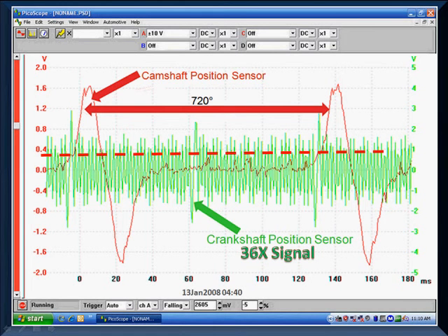Now, here's a high rate system. On the newer vehicles, when we get the coil on plug, we're going to have this type of system. Let's look for the signature patterns. They're here. In fact, there's several signature patterns. We put a dotted red line in here because we've got signatures going on in between the big signatures. But we've got a large signature right here. Notice at the time that one goes higher than the rest is at the same time the cam is coming from right at zero and starting to increase. That's identifying a number one TDC for us. This is important because this particular signal is used on a coil-on plug.